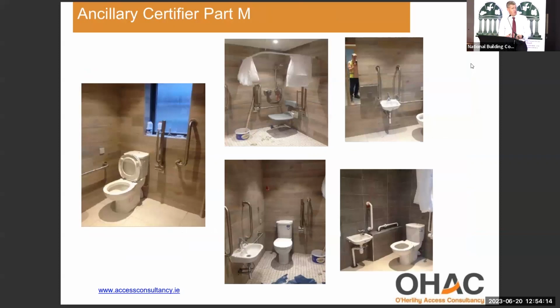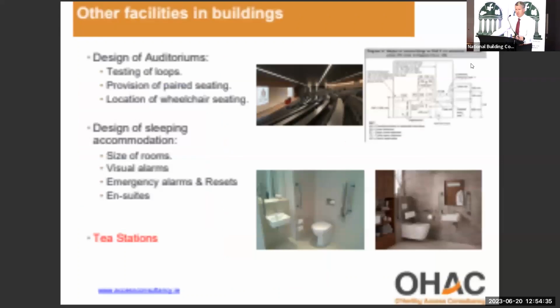And this image is just basically showing you 2 or 3 different toilets. But again, I'm not going to go into the detail here today, but simple things like the shower rail is too close to the corner here. It should be at least 500 and stuff like that. The alarm reset is in the wrong position, and the box outs are incorrectly designed and so on. Okay, so what can go wrong does go wrong here in the fit out of your toilets.